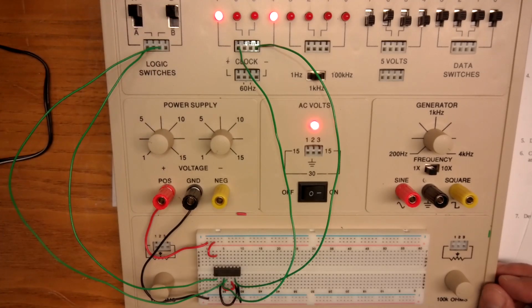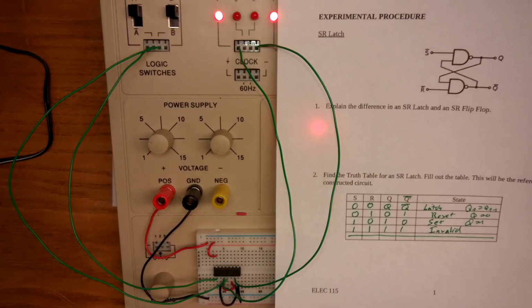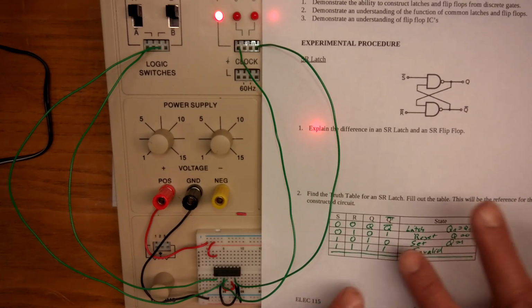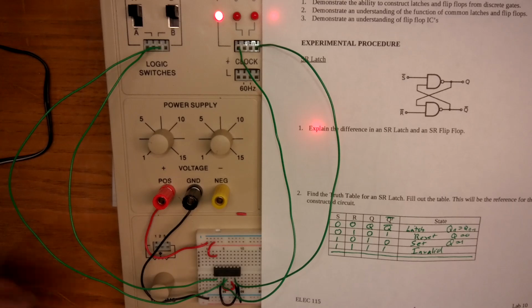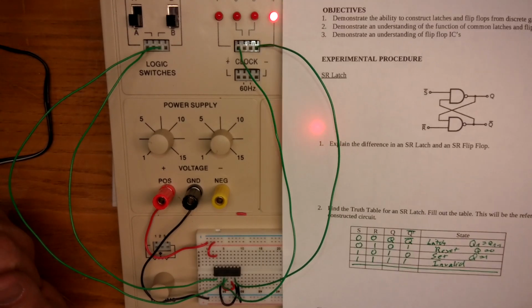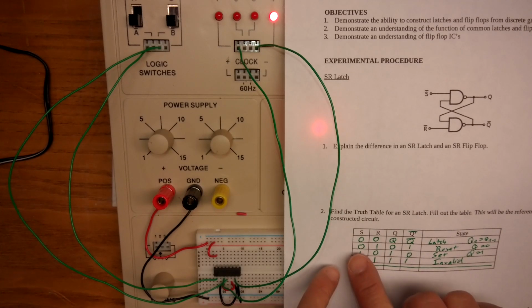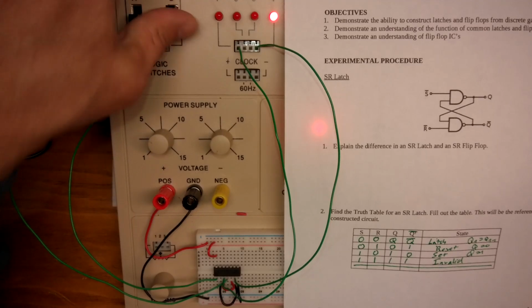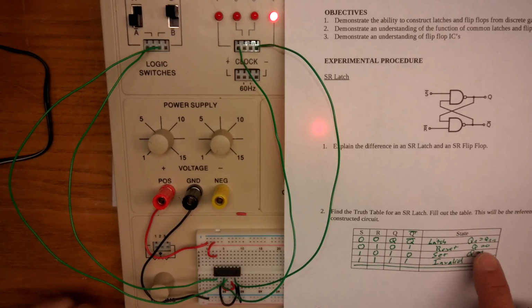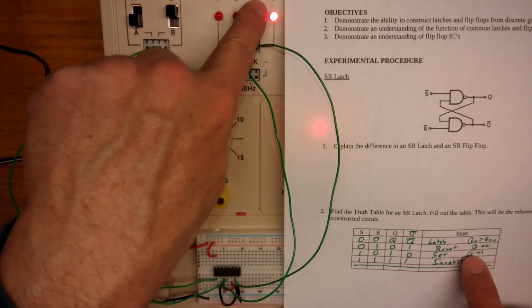Okay, there we go. Lights are on, so I'm going to go through and check this. You want to fill out that next truth table as you work through it, but I'll just check against this so we can see it. So if I start at the top, 00 is latch or memory. Hard to tell. So let's go down, because it's got to just keep with the last value. So we'll check it as we go. So we'll go down S0 R1. 0, 1. That should set this Q to 0, Q0 to 1.